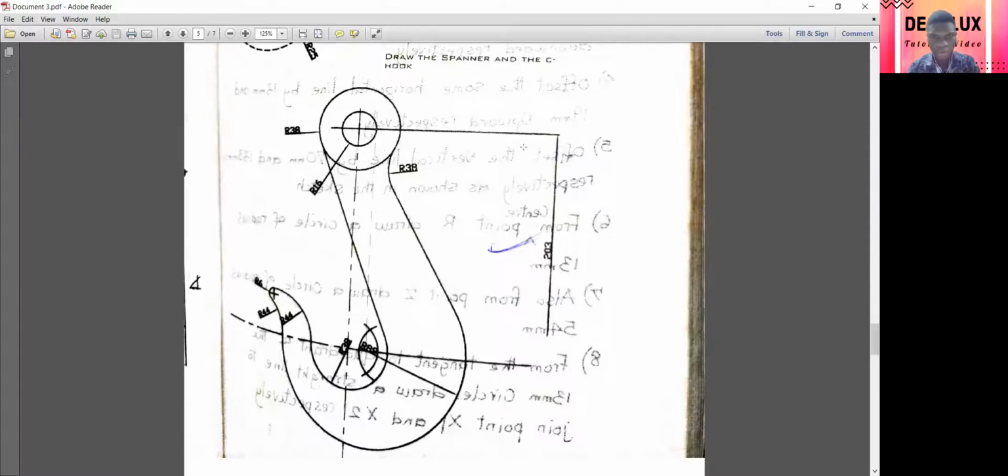And that is we are going to draw this line. There is a line here before this arc. Don't forget there is a line. This line was a continuous line. It was only trimmed. And there is a line tangent to this circle, and tangent to this inner circle.